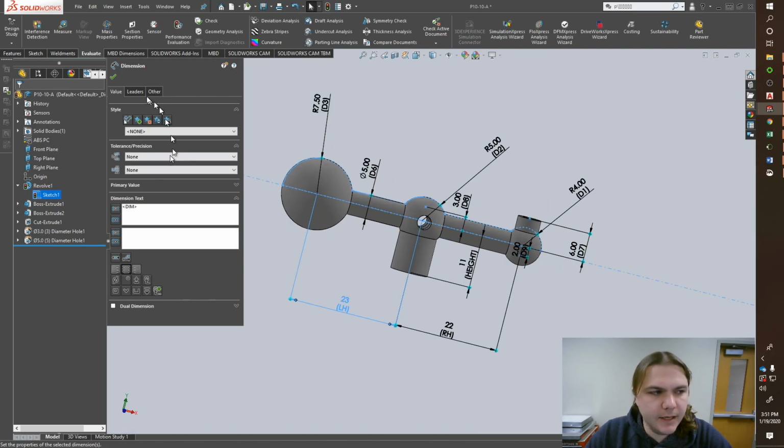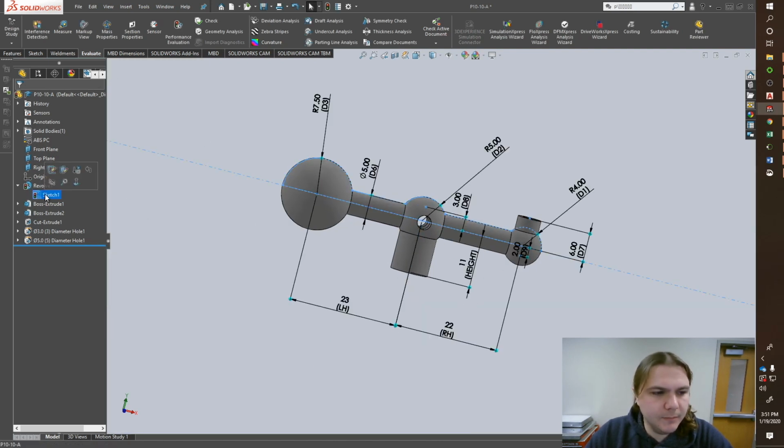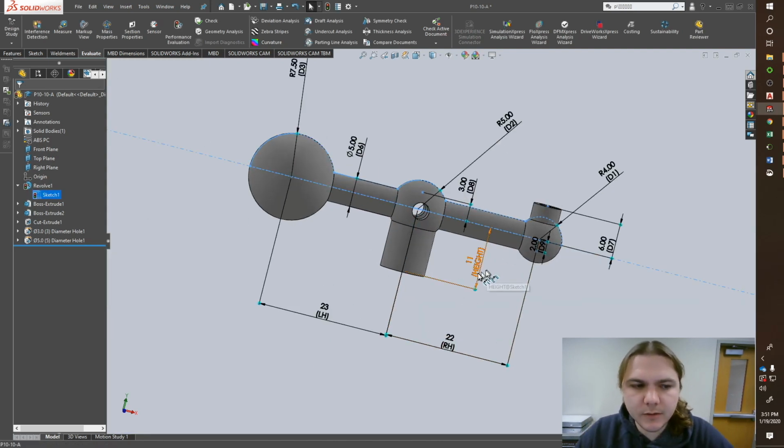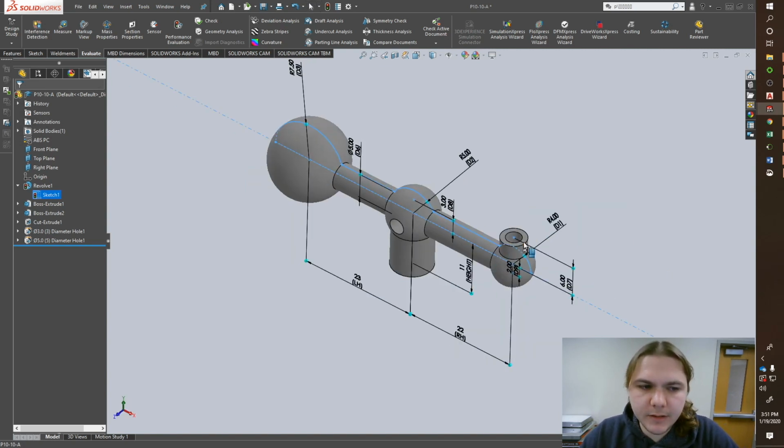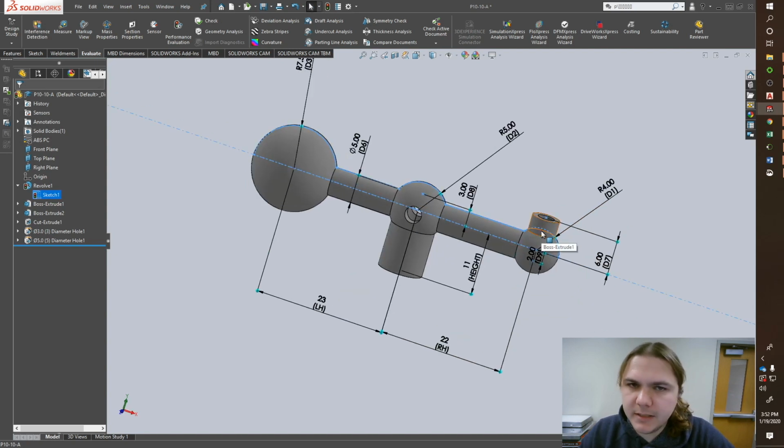The height, on the other hand, I had to put a little thought into. When I changed the overall height here, I wanted to make sure that this cylinder coming out of this sphere never became negative, I suppose. So if this ever went 8 or so up, this also stayed 6 from the center of that feature. That's why I dimensioned it this way.